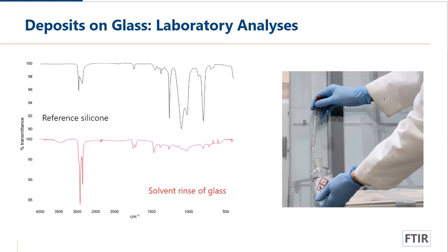Now, one of the concerns we have is that we know that there's a silicone perimeter sealant. And silicone is primarily silicon and oxygen. So it's going to look very similar by SEM EDS to the deposits. It could. And in many decades past, there were issues with silicone sealants that would bleed material out, that would lead to a sticky surface that allowed dust and debris to collect. And we wanted to make sure that that wasn't happening.